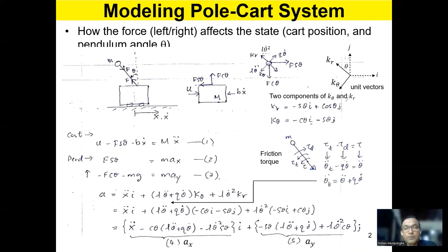Now, I want you to pay attention to this particular diagram here. This is very important. Now, you can see some inverted pendulum models freely available online. And sometimes you will not see the friction and drag coming into the model. Most of the models are actually not considering the friction and drag, etc. So that's why this part is very important, because I have included the friction in this modeling.